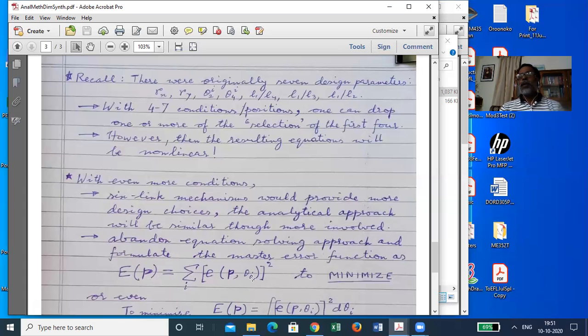Okay, so if you are looking for function generation from theta 2 equal to 30 degrees to theta 2 equal to 150 degrees, in that you want to design a nice curve for the theta 4 value. So you say that in this many intervals, or this many Chebyshev points we are going to take, say 2 degrees, 2 degrees, 2 degrees separation. Okay, 20 points, or you ask for 20 Chebyshev accuracy points.